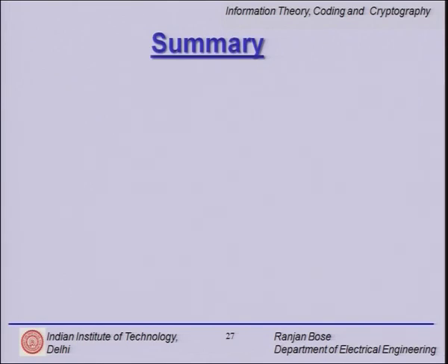All right. So we would now like to summarize what we have done in today's class. We started our discussion with the design of the optimum quantizer, which minimizes a predefined distortion function. We took an example of mean square error distortion. Once you get that distortion measure and you minimize it, you end up with the quantization levels. Now, your input amplitude is a continuous random variable with a probability distribution. Based on that, we associate probabilities with the different levels of the quantizer, and then we encode them using Huffman coding. So no two levels of the quantizer would yield an equal number of bits per sample.